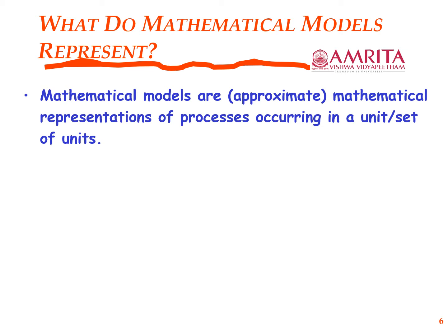And as with any crude distillation unit, there are multiple products. So at different intermediate stages, there are products that are removed, and then there are additionally side strippers. When the product's liquid stream is removed, there is a small distillation column in itself, where there is further enrichment of the product that is basically to be collected from that stream, and then the remaining part of it is sent back to the column.